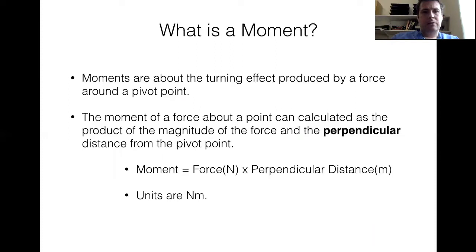So now we're just going to describe moments. So what are moments? Well, moments are about the turning effect produced by a force around a pivot point. And the moment of the force about a point can be calculated as a product of the magnitude of the force and the perpendicular distance from the pivot point.